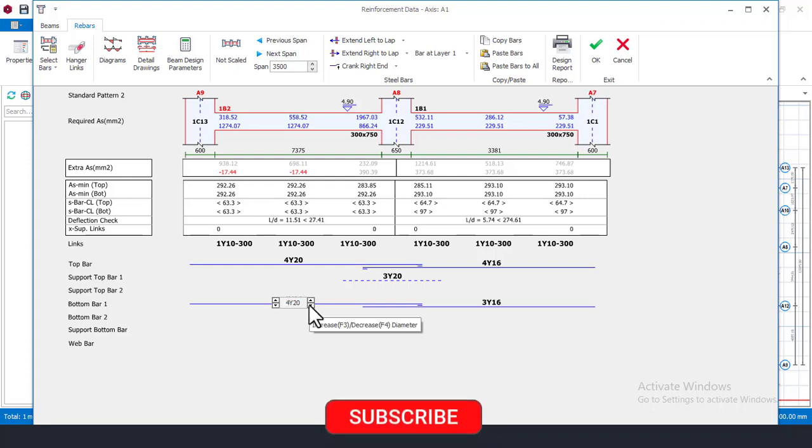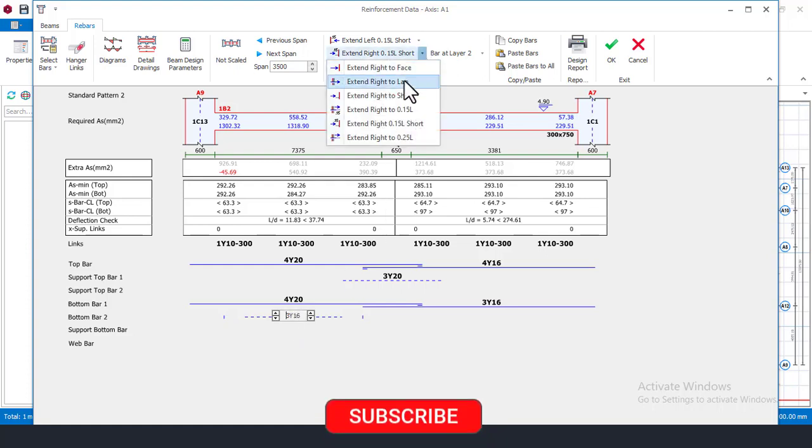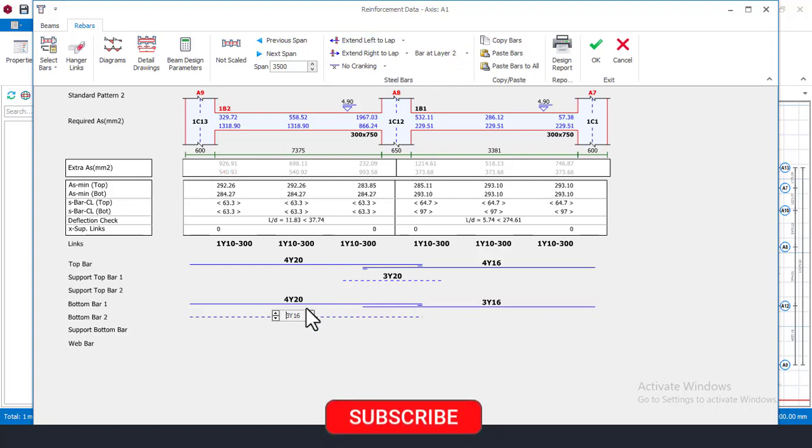And let me try, is it fitting here? It's fitting here. I have to try to add a bar here right now, bottom bar support 2, and then try to increase the number. Let me just try Y16. Yes, it's failing. I'll come here right now and say slab, and come here and then say slab. I need it to be okay now. Okay, let me try to do 2Y16. Let me see if that's okay. Yes, that's okay, that's fine.